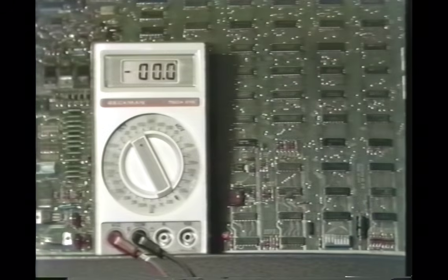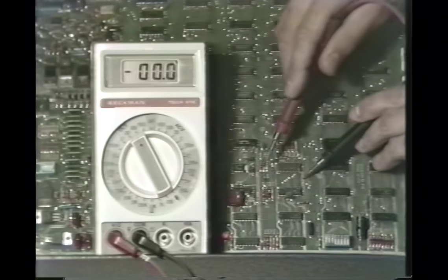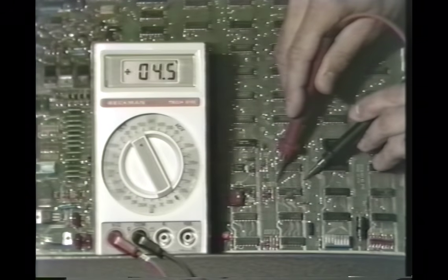Anytime you have bizarre problems with your game and you don't know where else to turn, start by checking the power supplies. Knowing that power supplies are responsible for a large percentage of the failures in games, our average mechanic checks the power supply across the power rails on the printed circuit board. But the meter doesn't read 5 volts. The meter only reads 4.5 volts.